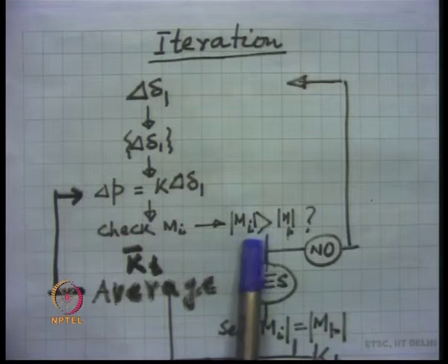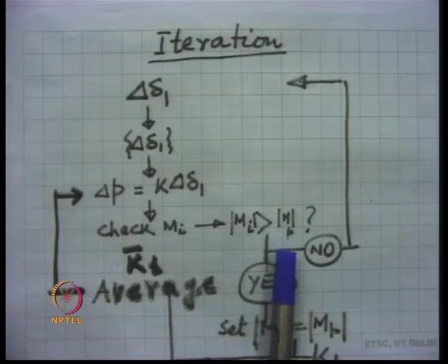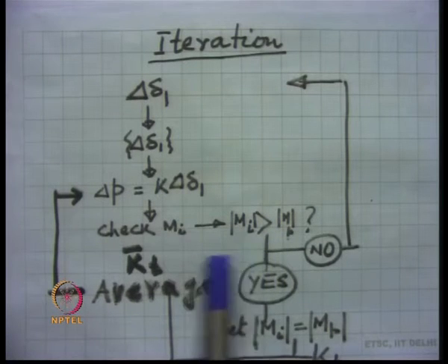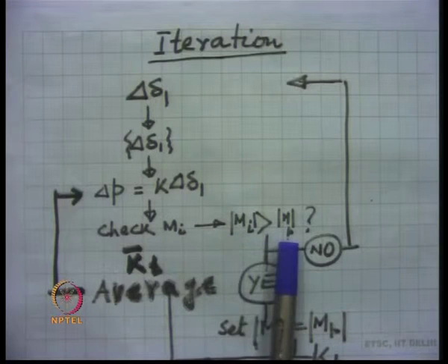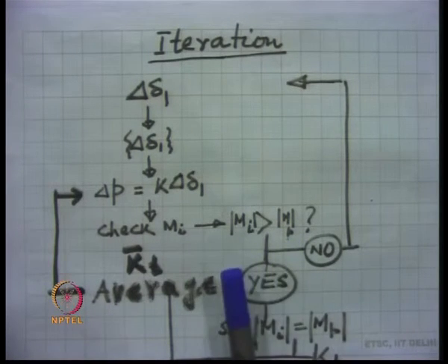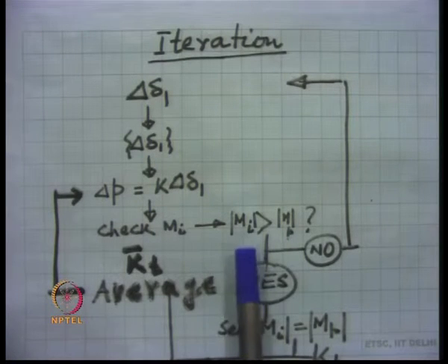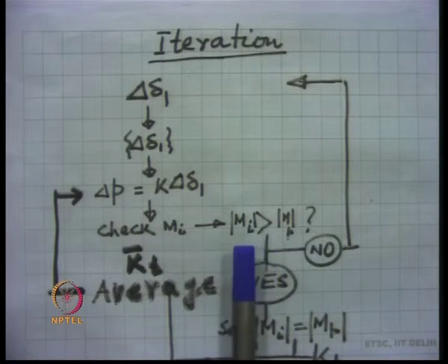The moment being just equal to MP is a rare case. Therefore, in most cases we find that the moment is greater than the value of MP. If it is less than MP, then of course that cross section is still in the elastic state.